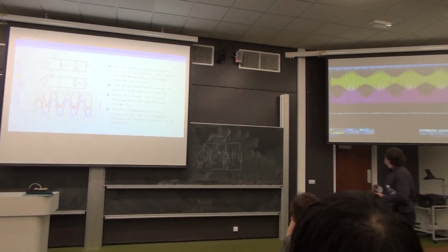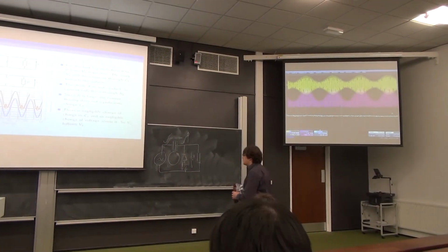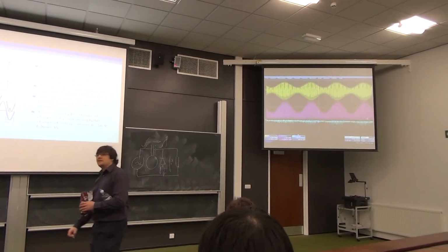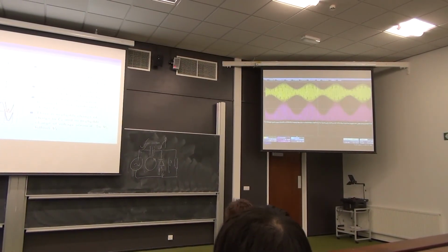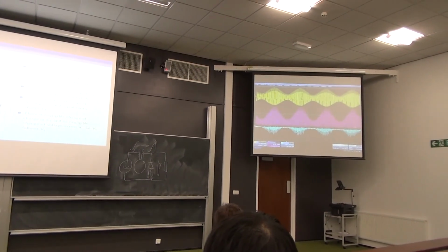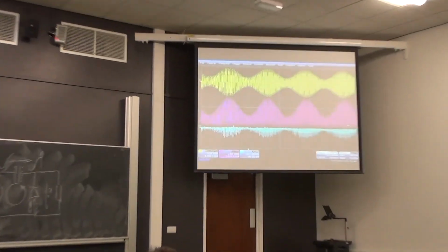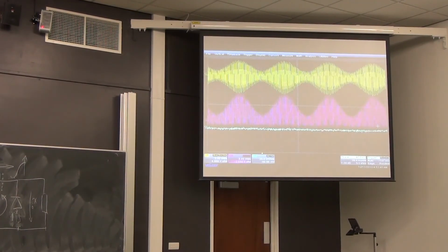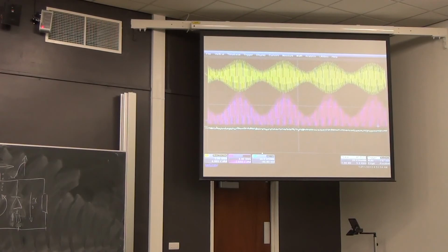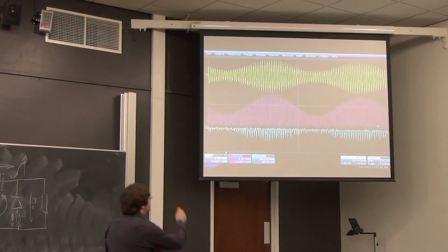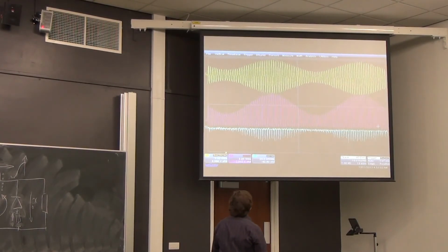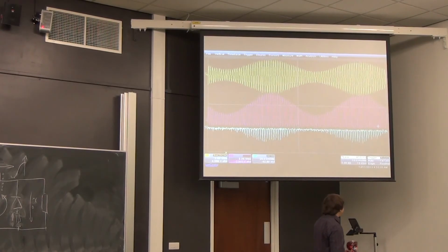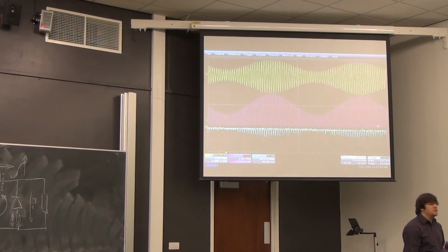So there we've got some AM at the top, and this is the same AM signal that we had earlier. It's 1 kilohertz. Is it 1 kilohertz? Doesn't matter if it's not. It's not quite the same AM that we had earlier. In the prior example, we had 200 hertz carrier, which is the high frequency in the middle. In this case, we're up to 1 kilohertz. But the modulation is still the same. We still have 20 hertz frequency, which is carrying the information, which is the longer period. And we can see that the output, which is in purple, is held at minus 0.7 volts at its minimum.